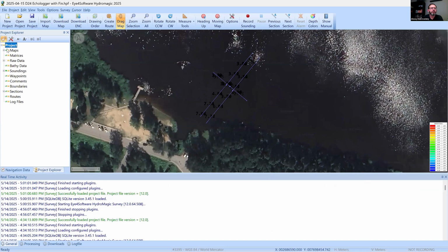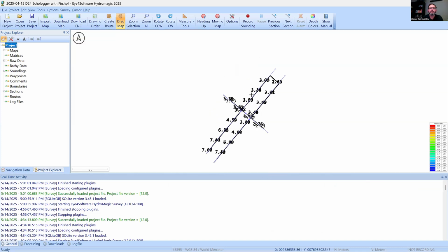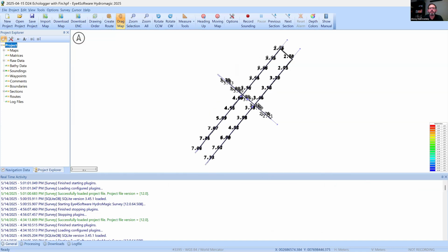We did a lot of repeatable surveys using different configurations and different speeds. For all surveys, we used check lines, a survey line perpendicular to a couple of regular survey lines. And we calculate the difference between check lines and the perpendicular lines, estimating the accuracy of every configuration.